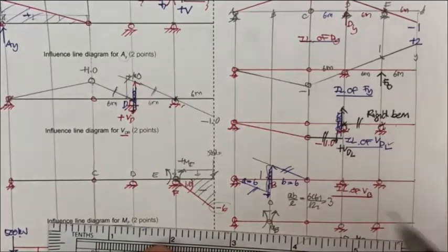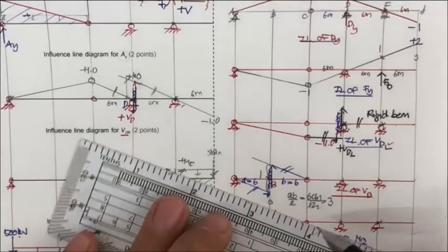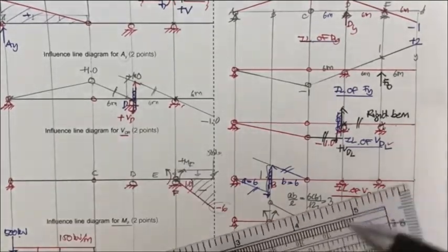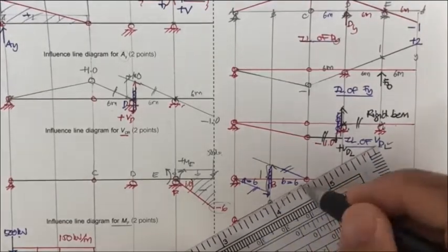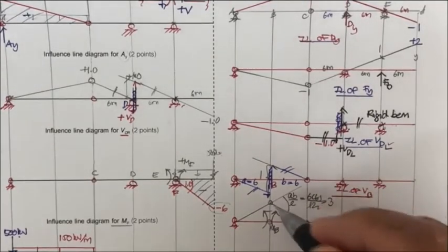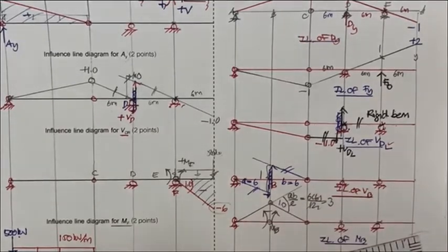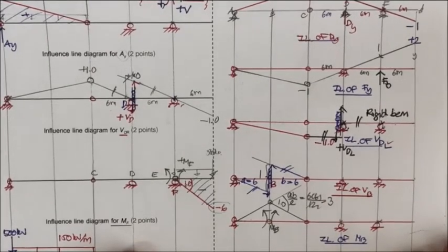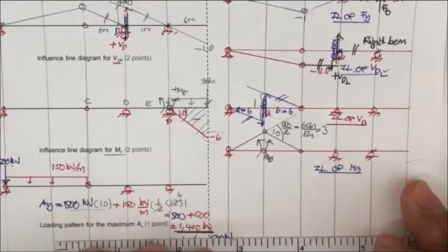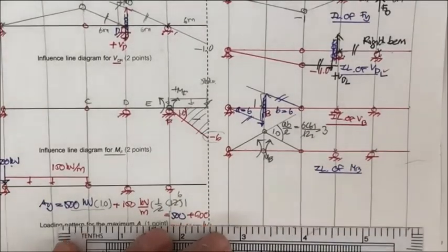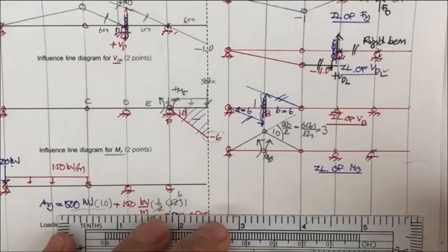And you get 3. Then let's move here for 3, and this portion has the roller and roller, so it cannot move, by the same lesson as before. This one is going to move up here, and we have the 1.0 relative angle here. That is kind of easy, right? And then if you like, you may move to draw the influence line of M sub D.